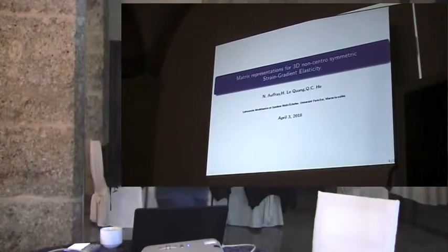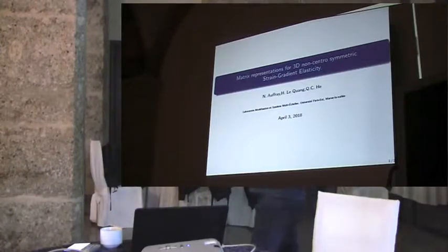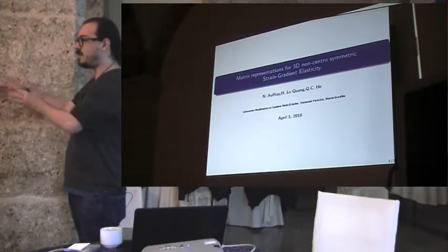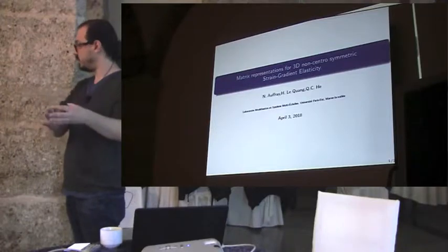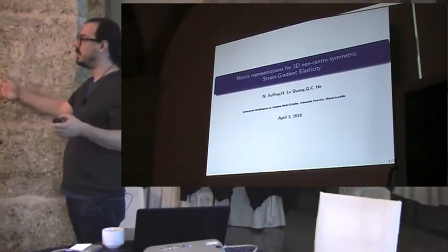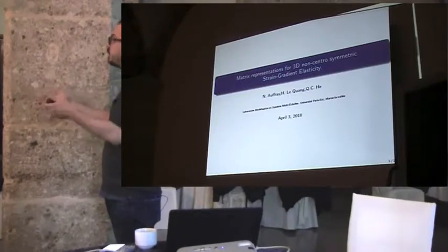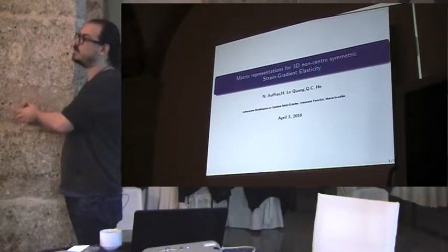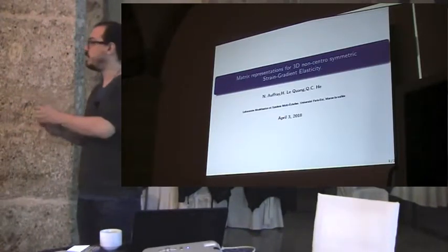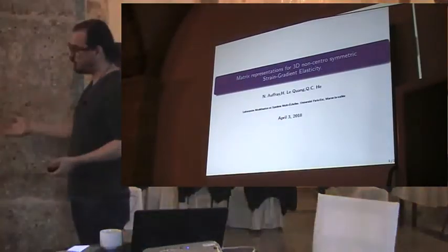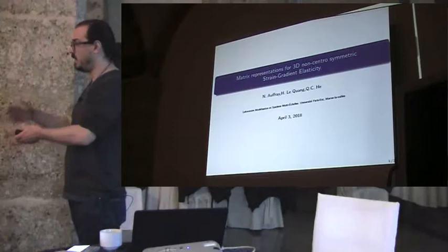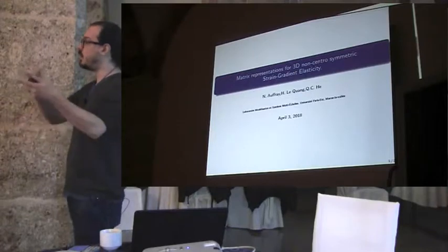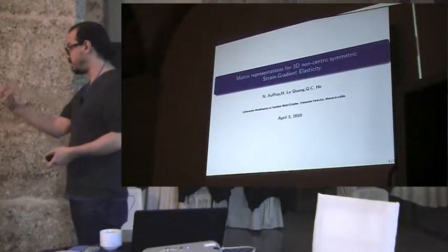So today we'll discuss the anisotropy of strain-gradient elasticity. Yesterday we heard that in its full setting, strain-gradient elasticity is defined by 300 coefficients, and in its isotropic setting it's only defined by 7 coefficients. The question is, what lies between these two extreme situations? We will show that between no symmetry at all and complete symmetry, you get 48 possibilities defined by different numbers of independent coefficients, each one associated to a special symmetry class.